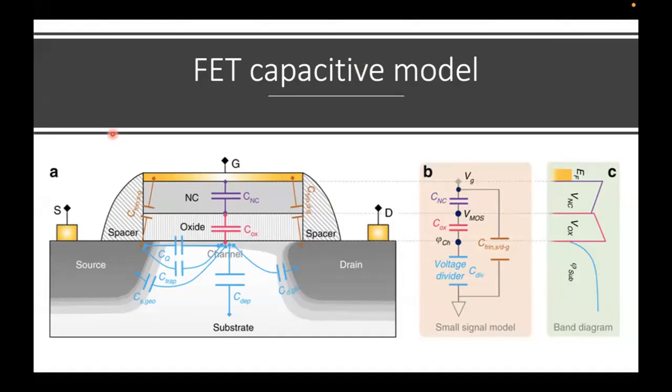A third source for a capacitance might be a diffusion capacitance from having two layers of different doping. So having two layers of different doping can also include some sort of a depletion region in the energy band diagram, which results in a capacitance. So let's see this.